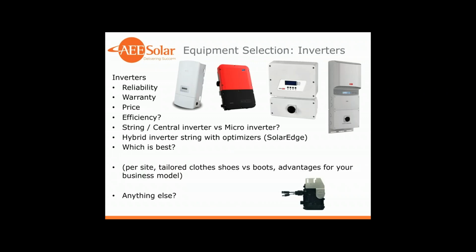For solar inverters, this is one that I definitely have some strong opinions on. I'll typically ask a given partner what inverter they use, and a lot of partners will say, oh, I use inverter A. Maybe I just use Enphase microinverters, or I just use SolarEdge. And I'd argue that that's actually kind of a mistake. Really what you should do is use the appropriate inverter for the given job site.